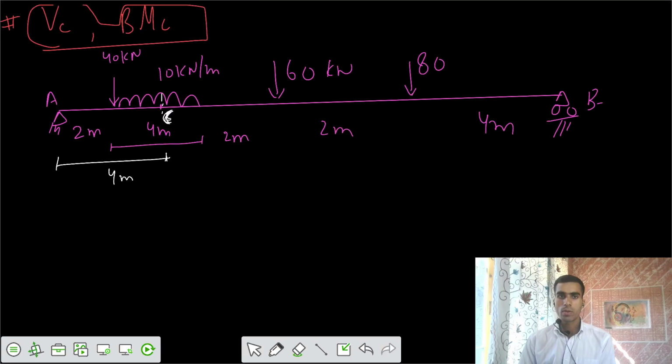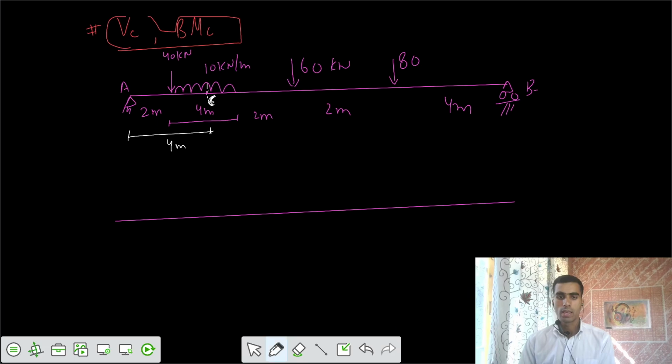So if I talk about shear force, can you draw the shear force diagram? I would say, can you draw the ILD for shear force at C? Since your beam is simply supported, I would say the diagram looks in this fashion. Let's have that straight line. For the first part, you have to go downward shear, and in the next case you have to go upward shear. In a simply supported beam, you just lift those, and after that join by a straight line.